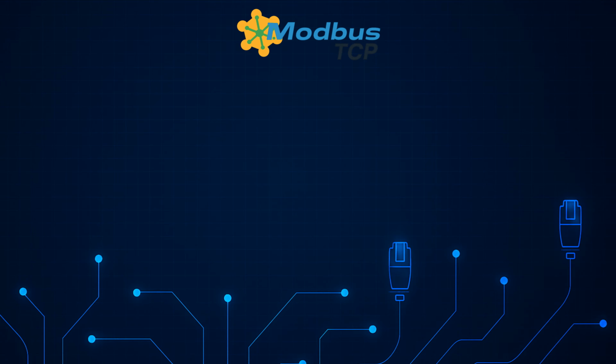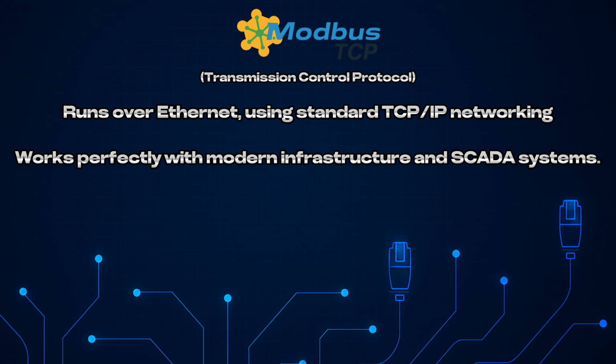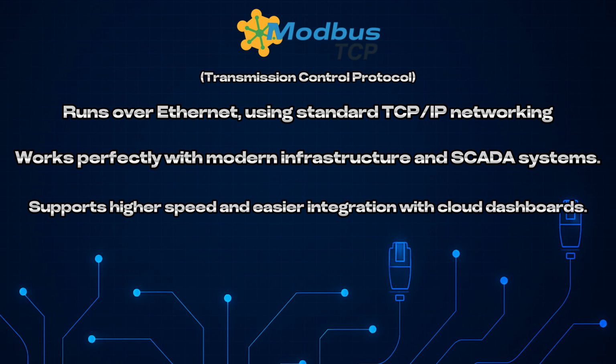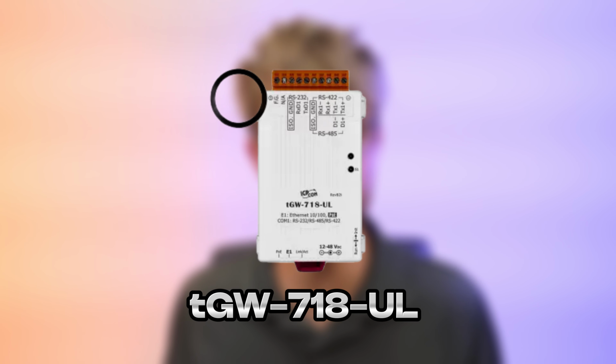And Modbus TCP, or Transmission Control Protocol, runs over Ethernet using standard TCP/IP networking. It works perfectly with modern infrastructure and SCADA systems, and it supports higher speed and easier integration with cloud dashboards. And the best part is they can actually be bridged together. For example, a TGW series Modbus gateway can connect older RS-485 devices to a modern Ethernet network, letting you integrate decades-old equipment into a smart connected system.